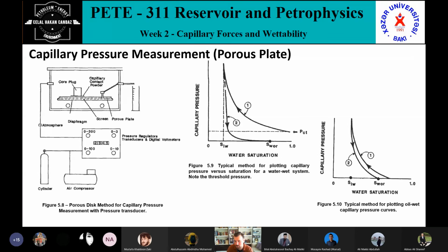So these are homogeneously made pores, with the blank empty parts between the pores very fine. One of the rules is that the permeability of the disc should be at least 10 times lower than the permeability of the core. If the ratio is less than 10, there can be some errors in measurement. At least 10 times lower it has to be.